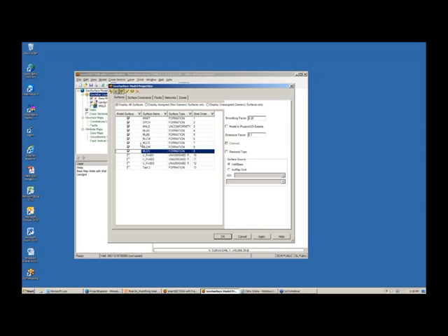Another very important feature that we've recently added is that you can equate one of these surfaces to an isomap grid. So if you've got either a hand-contoured map or a seismic map, a time-depth converted seismic map that you've brought into Geo Atlas and that you've done a contour-to-grid function on, so that you've got a gridded surface, you can equate a smartSECTION surface to any gridded surface and actually view that surface in the cross-section. So it's a very powerful tool.